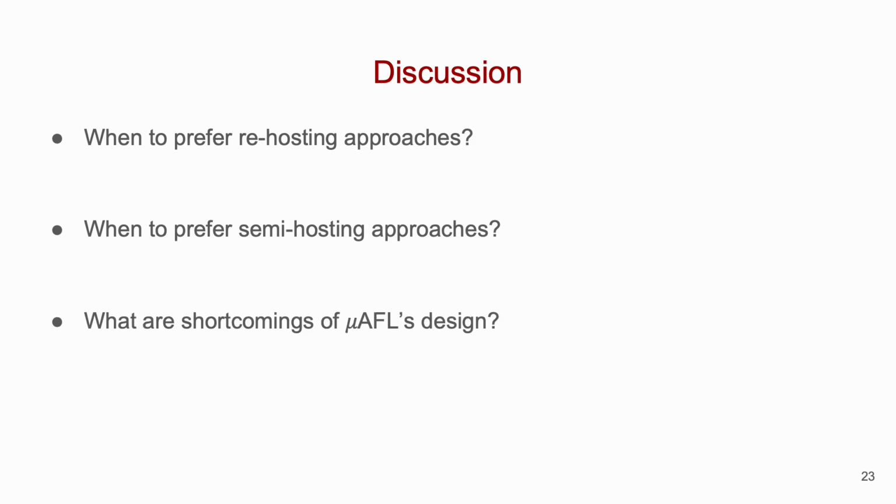Next, based on all of our discussion, what do you think are some shortcomings of mAFL style semi-hosted fuzzing? Well, first is obviously while mAFL allows fuzz testing directly on real hardware, it is only specific to ARM devices that provide support for ETM tracing. It will not work with any other vendor or ARM devices that do not support ETM traces, unless ETM or similar technology is supported by those vendors.